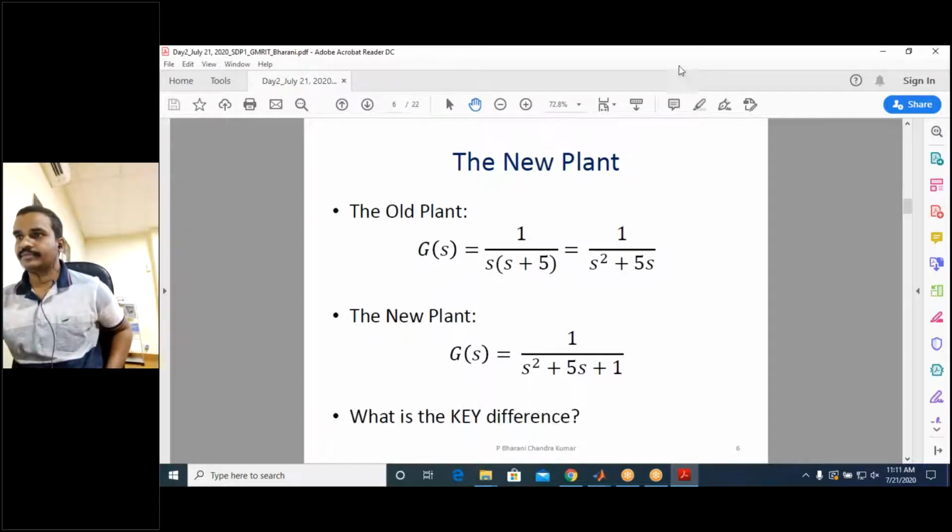Sir, for proportional gain we can implement with a resistor, but what about integral and derivative gains? What is the practical hardware model? It is very simple. For integral, you can use the capacitor, 1/C integral of i dt. For derivative, you can use the inductor, L di/dt. Like that, you can do the physical realization. It is as simple as that. Thank you.